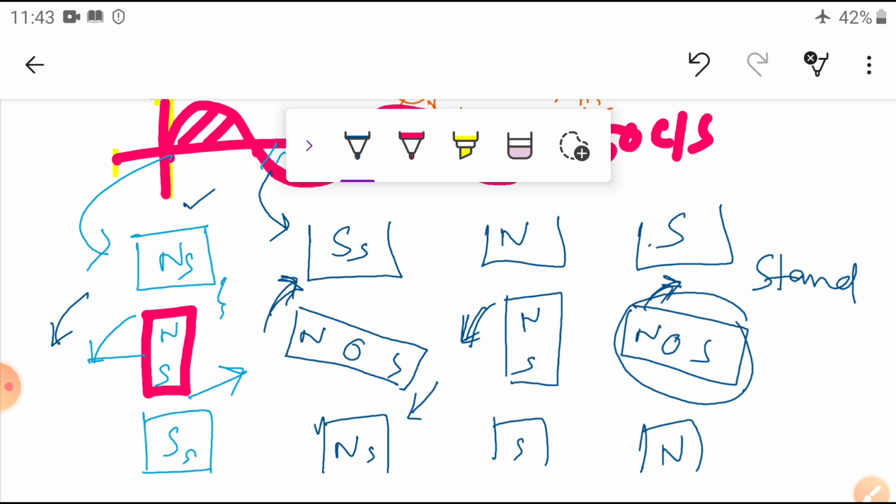Hence we can say that the synchronous motor is not a self-starting motor. Inherently it is not self-starting. Why? Because we have given the AC supply to the stator and DC supply to the rotor. Even so, a three-phase supply is given to the stator and plus and minus DC supplies to the rotor. So two types of supplies are given to our motor, even then it is not starting initially. That's why it is a not self-starting motor.